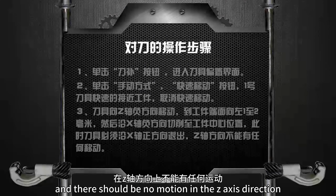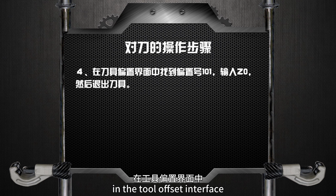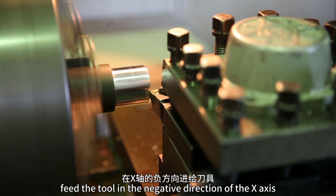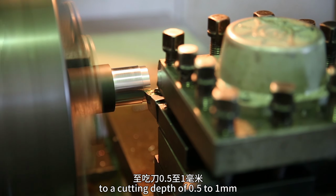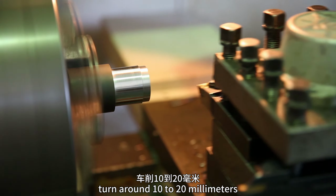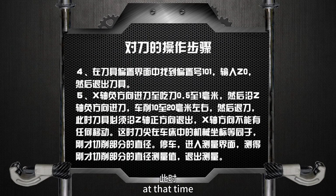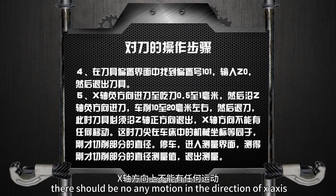the z-axis direction. Fourth, find offset number 101 in the tool offset interface. Input Z0 and retract the tool. Fifth, feed the tool in the negative direction of the x-axis to a cutting depth of 0.5 to 1 mm. Then feed along the negative z-axis direction. Turn around 10 to 20 mm. And then retract. At that time, the tool must exit in the positive z-axis direction, and there should be no motion in the direction of the x-axis.